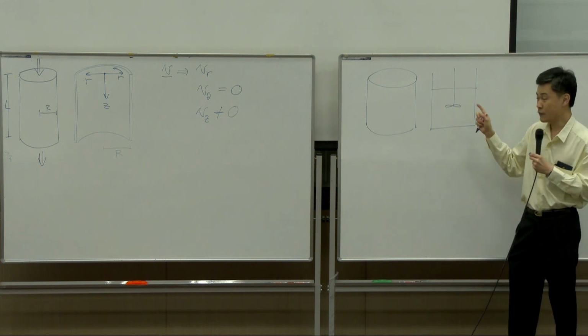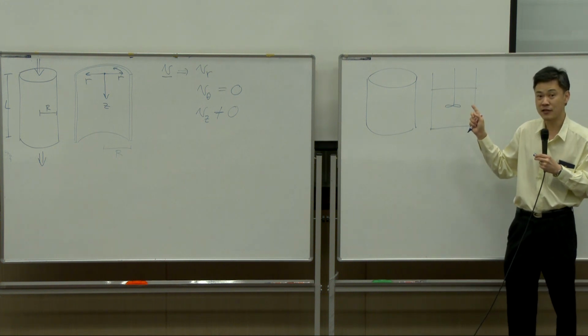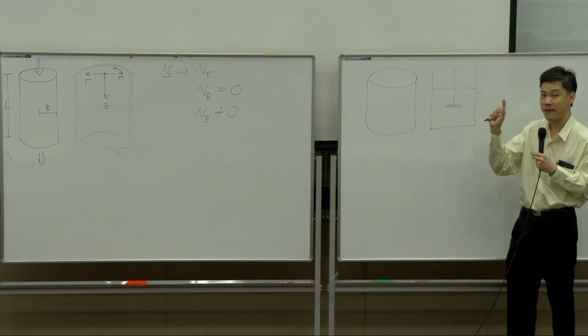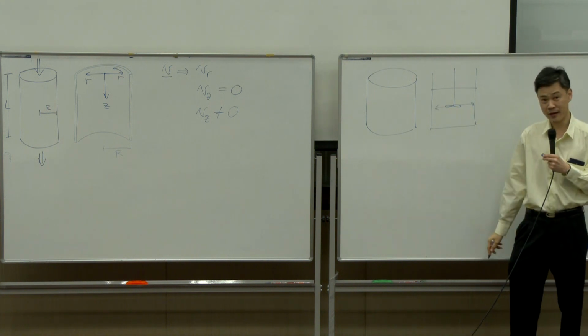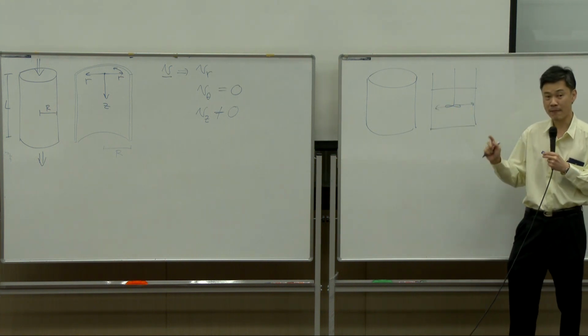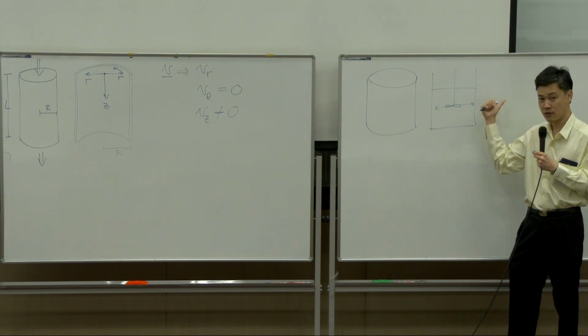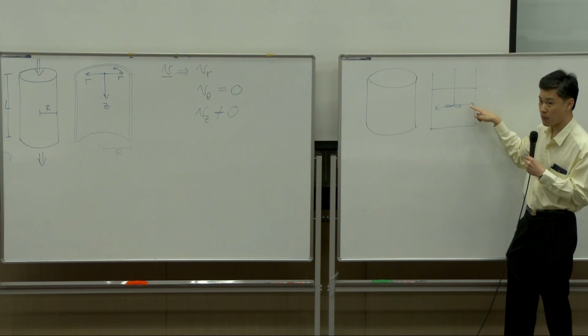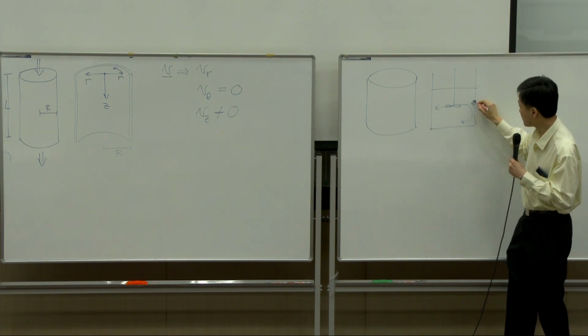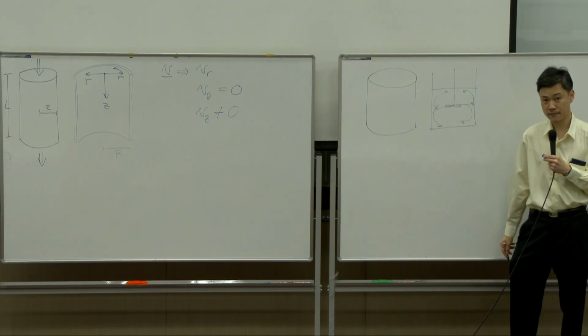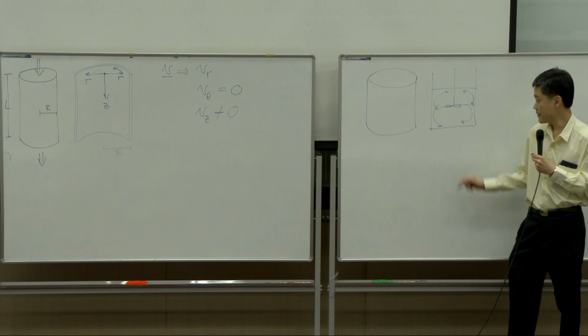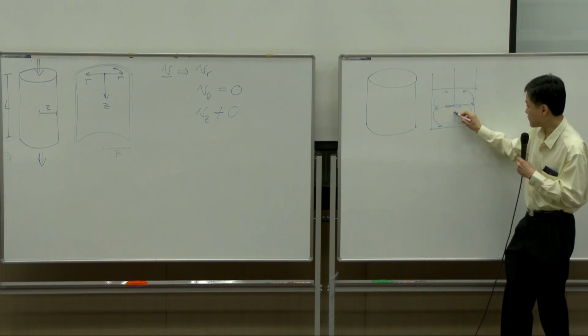Different blades give you different velocity distribution. For instance, if you have flat blades, the fluid goes this way, right? If you have a propeller blade, it goes outward. Once it hits the wall, it goes down, like this, and circulates back to the center.